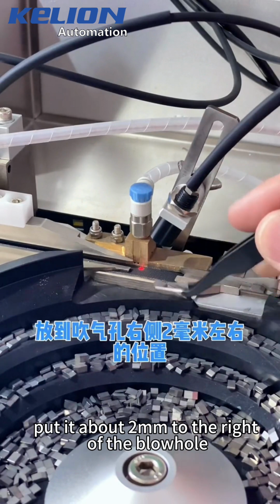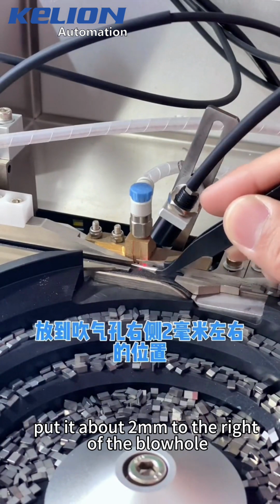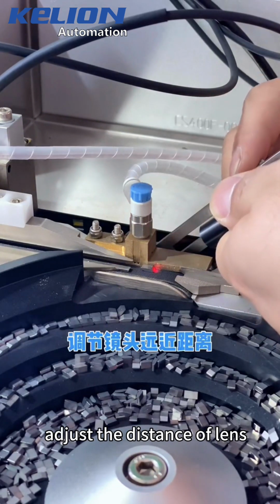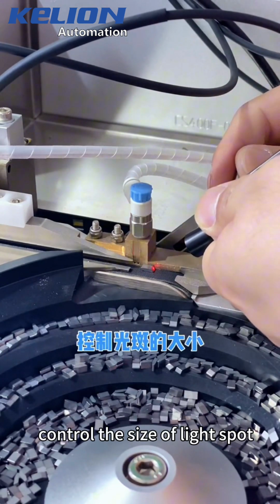Take a carbide tip. Put it about 2 millimeters to the right of the blowhole. Rotate the lens until the light is vertical to the carbide tip bevel. Adjust the distance of the lens. Control the size of the light spot.